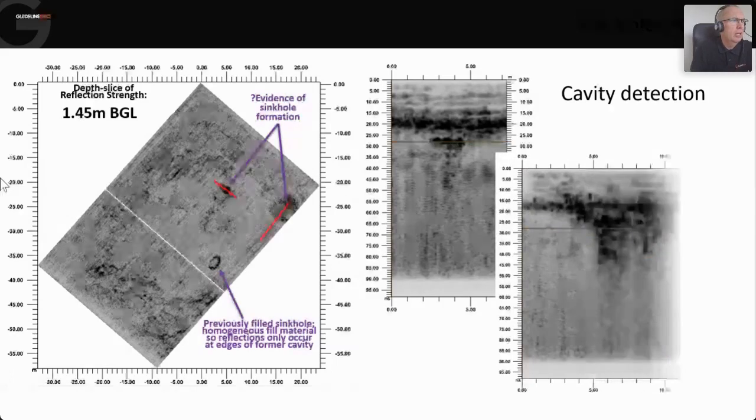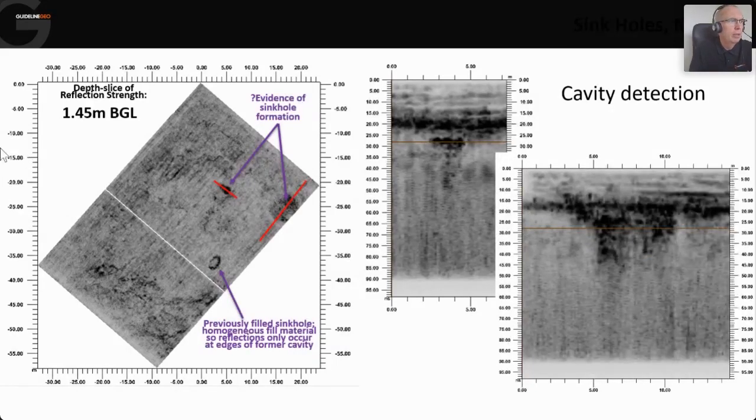And in a cross-section across this other darker feature in the time slice here, you can see quite a distinct change in the ground conditions around that area. That would then lead on to further investigation on that area. So that enables us to cut down and target testing with the system. So they can go in with boreholes or core samples to take measurements of the subsoils just to double check what's actually happening down there.